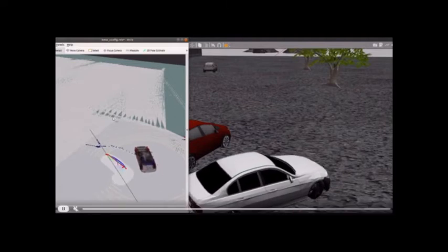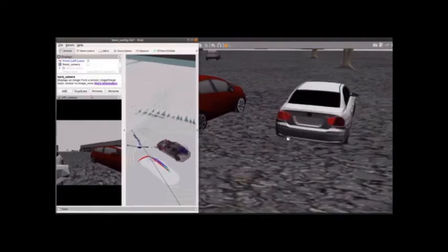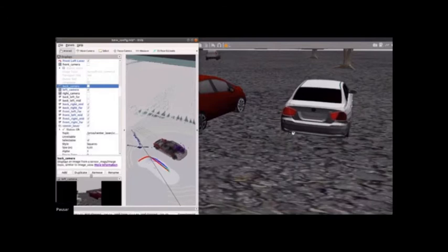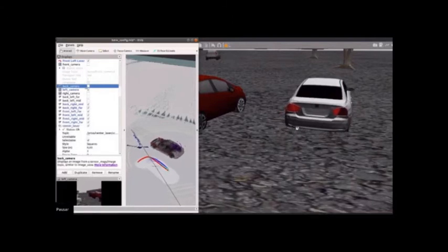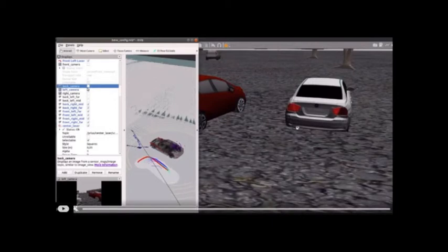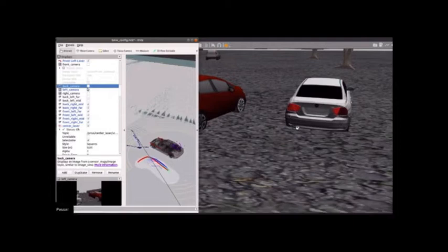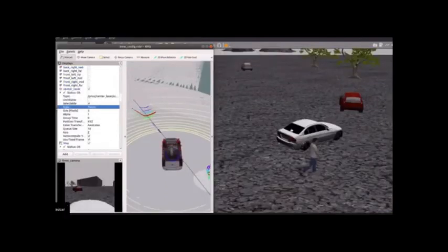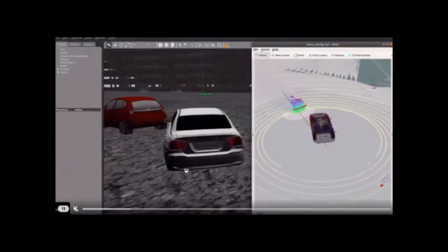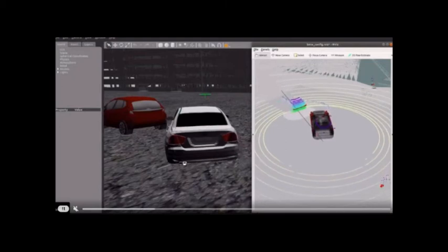As I said at the beginning of the presentation, there are algorithms feasible under non-holonomic and kinodynamic constraints, and this is one feasible path planner, and the other ones are unfeasible for this geometry, for this vehicle. They are feasible for other kinds of robots, industrial robots that turn around Z, and not the car-like vehicle that follows the Ackermann constraint.